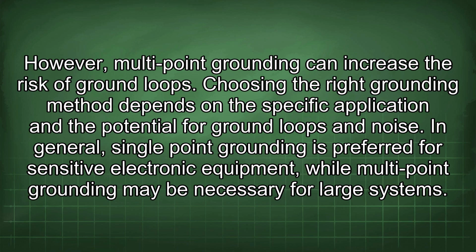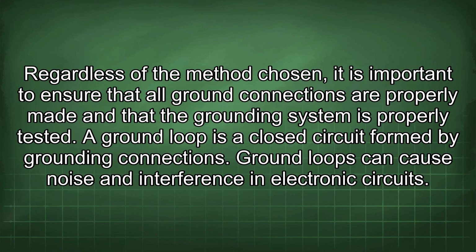In general, single-point grounding is preferred for sensitive electronic equipment, while multi-point grounding may be necessary for large systems. Regardless of the method chosen, it is important to ensure that all ground connections are properly made and that the grounding system is properly tested.